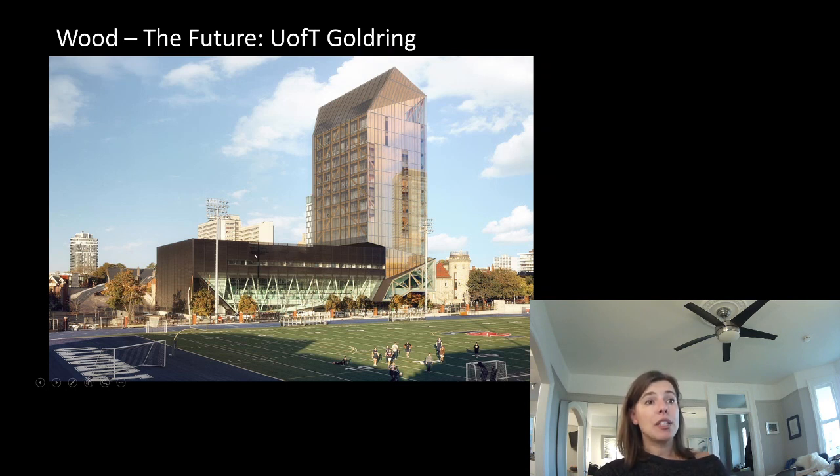This is the one where I actually did this steel project here, and at the time I had to design it because the basement for these two is connected. And in fact, the elevator for this is part of the elevator core for the tower. So when I designed the elevator core for this and the foundations, this was an unknown tower. U of T said, okay, assume it's some many-storey building. But you can imagine where the braces go, where the core goes, what the plan is, what the layout could change absolutely everything. So I had to get really creative to not limit future construction options.